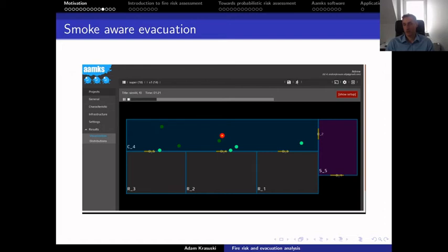Even for the separate smoke and evacuation analysis, this ASET-RSET analysis, the mostly applied approach is minimal smoke exposure. So these critical values, which we discussed in previous slides, are defined on such a level. For example, the temperature is defined at 60 degrees Celsius, and this value is not the zero smoke exposure, rather the minimal smoke exposure.